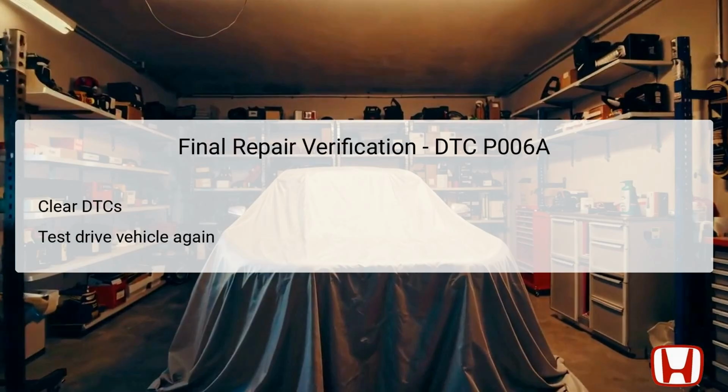After completing all troubleshooting steps and making necessary repairs, the next step is to verify that the issue pertaining to DTC P006A has been resolved. Begin this process by clearing the diagnostic trouble codes using the Honda Diagnostic System, HDS, which resets the DTC status. Following this, an extensive test drive of the vehicle should be conducted.